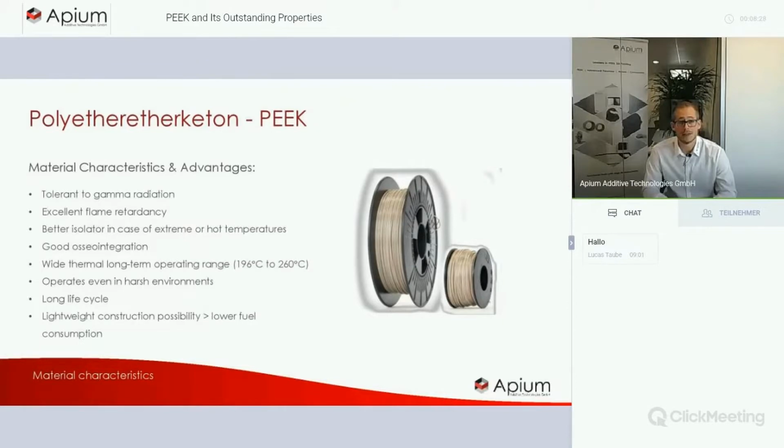We also have excellent flame retardancy. This is very interesting in terms of aerospace application. So PEEK won't start to burn itself, it will rather melt, and doesn't add additional energy when it comes to a fire. Then it's a very good insulator in case of extreme or hot temperatures.